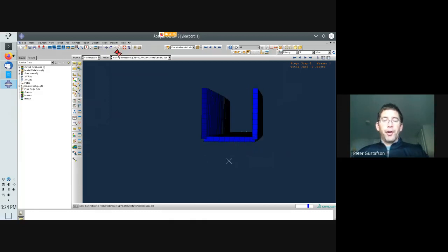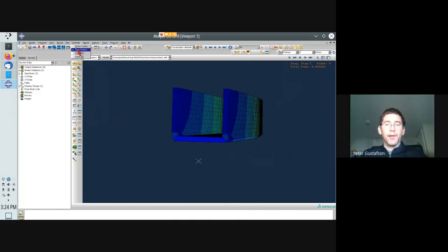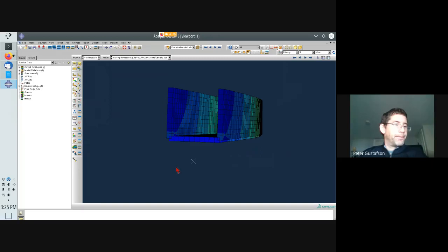This particular load that I've applied gets us pretty close. Let me pause the time history. You can see this thing is basically just bending now with no twisting. So visually, the load applied at this location where the X is, bend, no twist, that's the shear center.